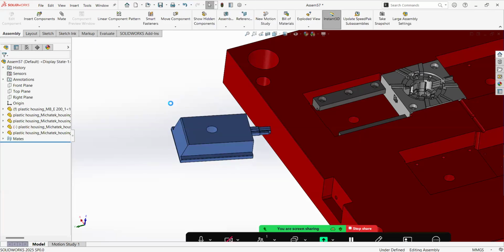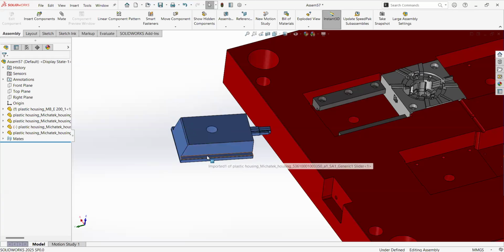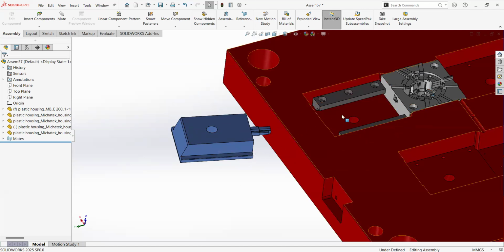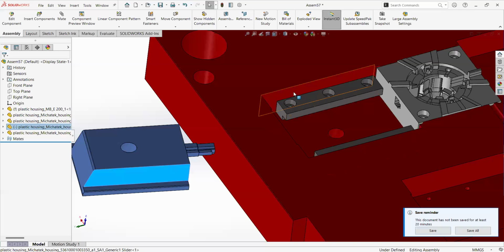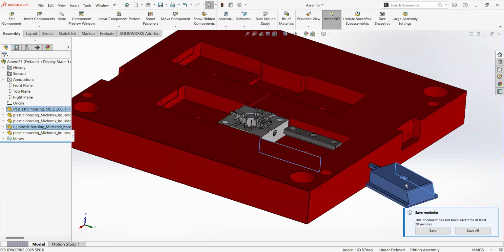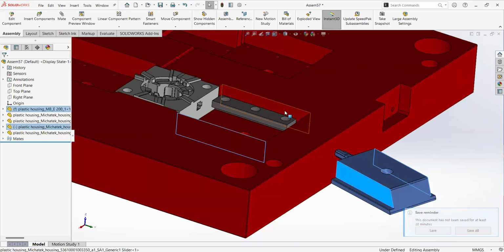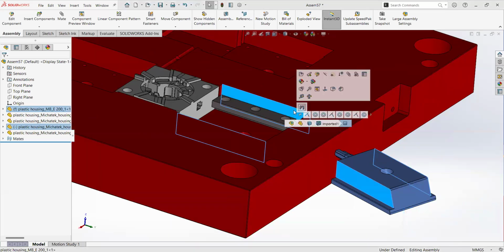And let me show you another one that is the width. This one, I use it a lot. For example, this carriage is expected to be center in this sliding movement. So I will pick this face, this face with the control. I will rotate, press again the control, and pick this one and this one. When I release, SolidWorks is interpreting the selections and gives me an option.